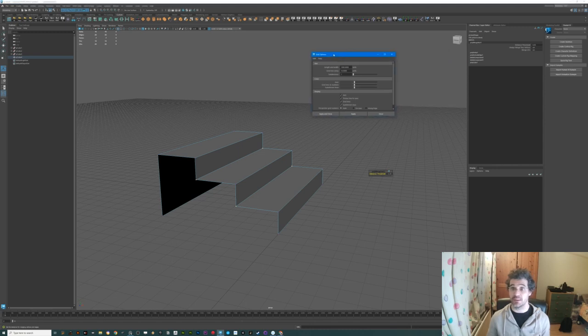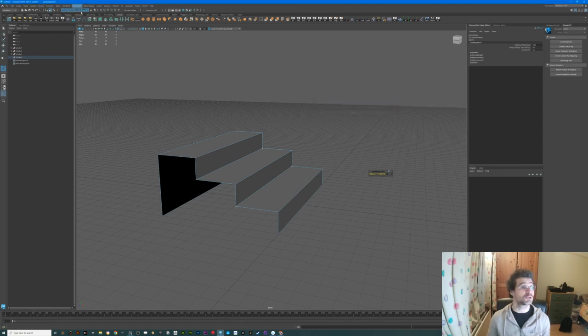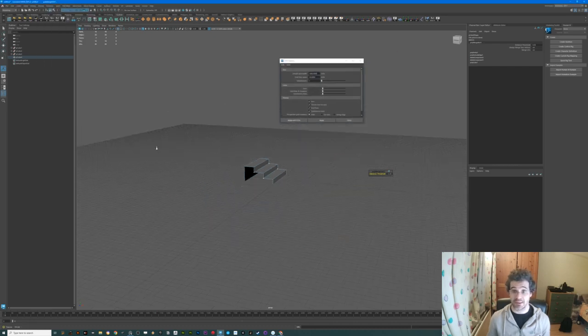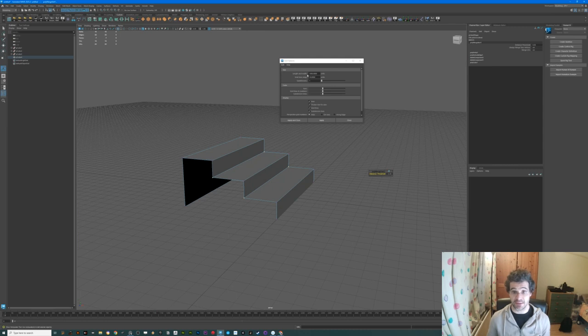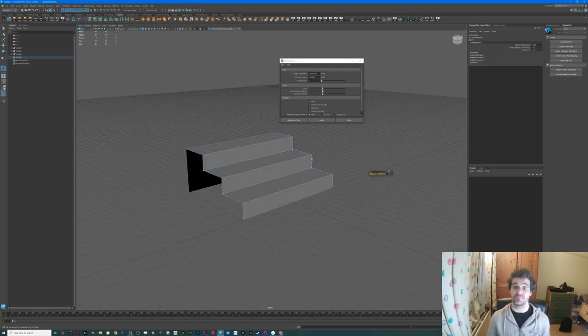Okay, so another thing I want to show you while I'm at it, if I come here to display grid, and I come here to the options box, you can see my grid alignment. Its length is 1,000 units, grid lines every 10 units with subdivisions 1. This essentially means that every single thing you see here is a 10 by 10 cell, which I normally use since everything I want to do is ultimately to export to Unreal Engine. I want to be compatible with that.